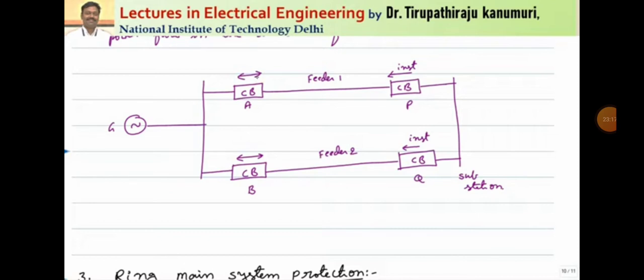So we have seen in module number 3 that the non-directional relay operation is very simple and cheap when compared to the directional relays, because a directional relay needs 2 sections, so the cost increases. So wherever it is possible, we always prefer to go for non-directional relays because the cost decreases, and simplicity and maintenance cost, everything will be less.